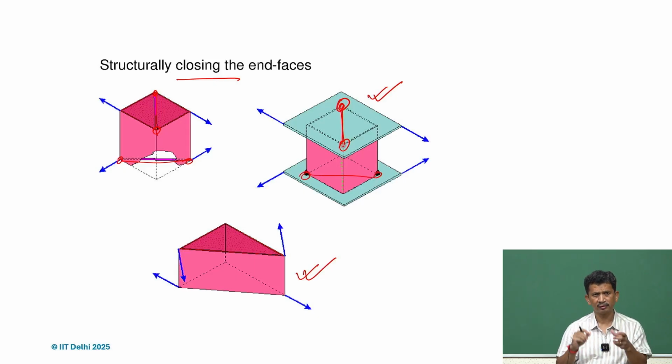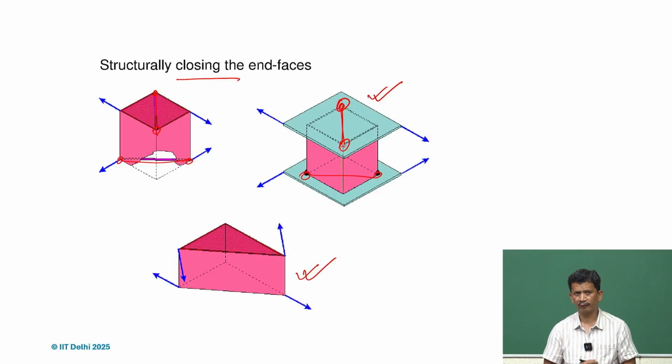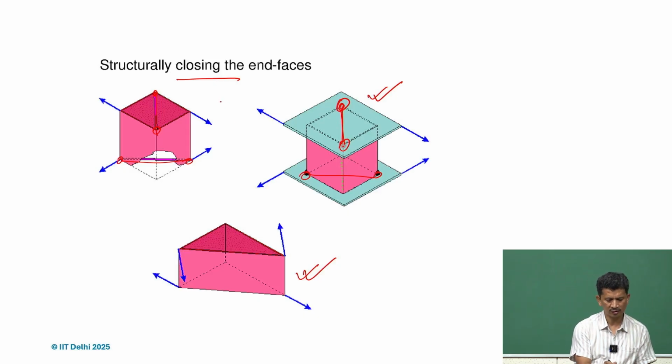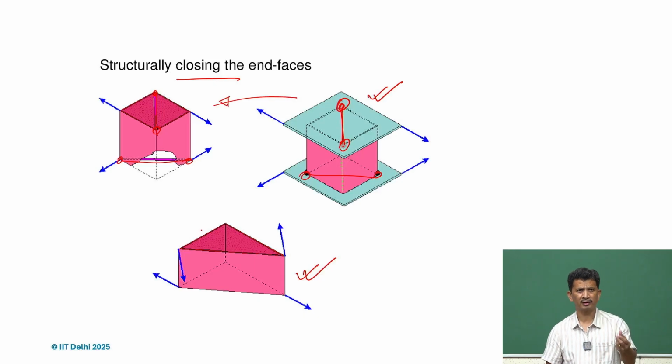So just tag one welding, we don't have to weld it all along the surface, but just at those two points, and it's very important to understand why it's required there. I think it's also from a fabrication point of view, and although we have the plate, essentially what we are trying to do is achieve this just by tagging at those corners.